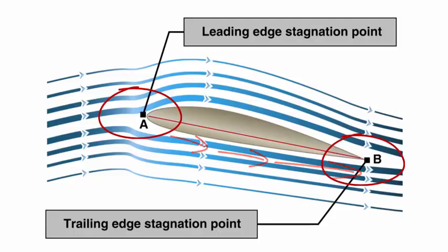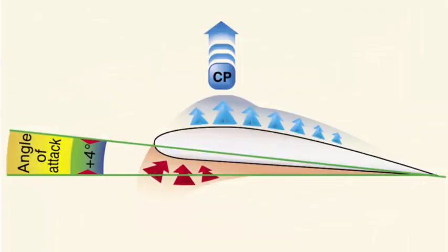surface. Again, applying Bernoulli's principle, where the airflow was slowed beneath the wing, a pressure was increased and positive upward pressure was created. Both Bernoulli's principle and Newton's laws are in operation whenever lift is being generated by an airfoil. The angle of attack of a wing is the angle between the chord line and the flow of air against the leading edge of the wing.